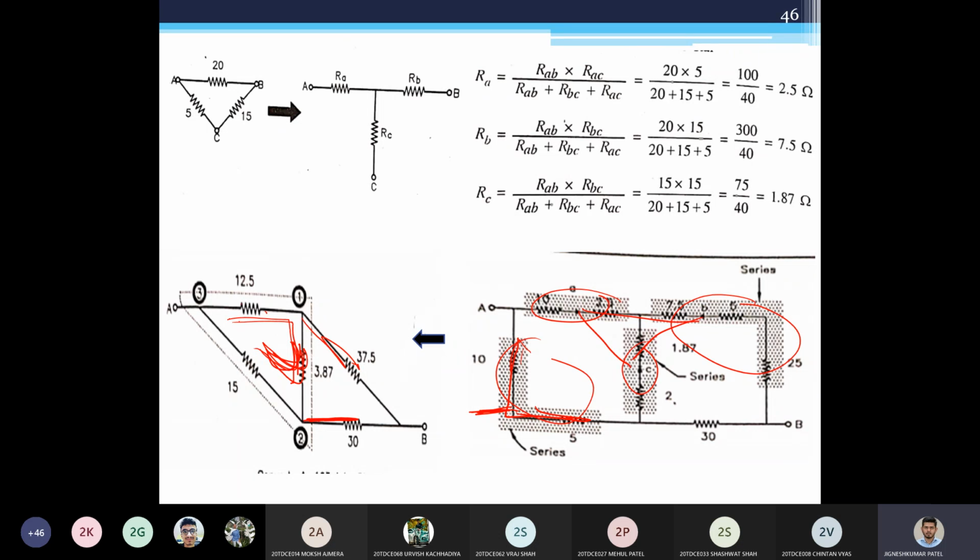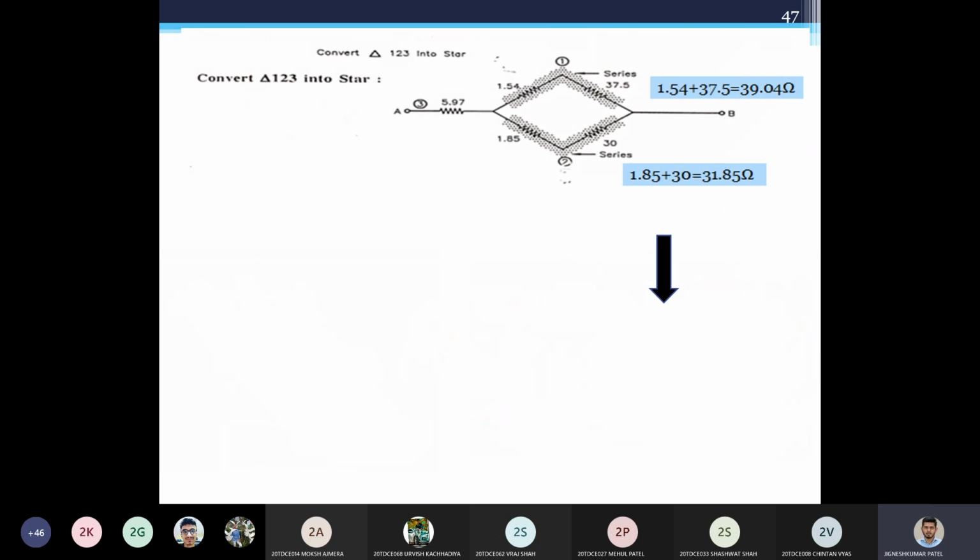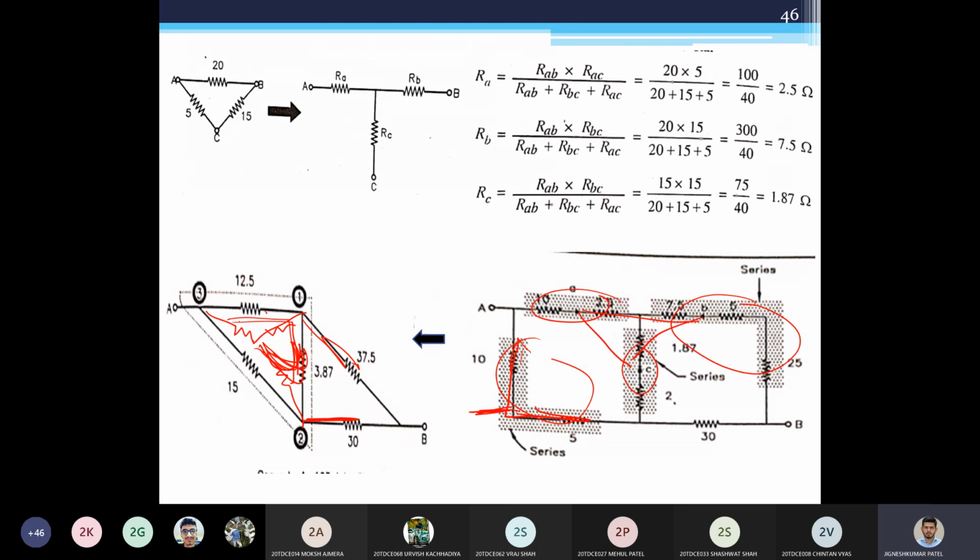This is actually a delta. Again, I'll convert this delta into star, so my star will form like this. There is one more branch like this. Let's see a simpler star, how it will look. If I redraw it, it will look like this. This would be my first point. I am dismantling these two and drawing a new line. So this is point 3.